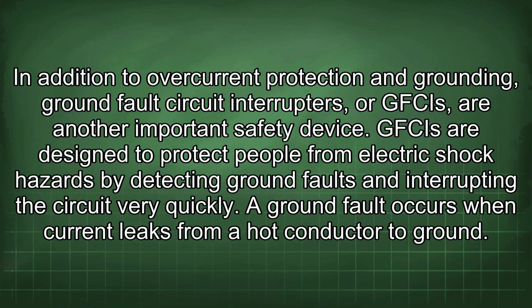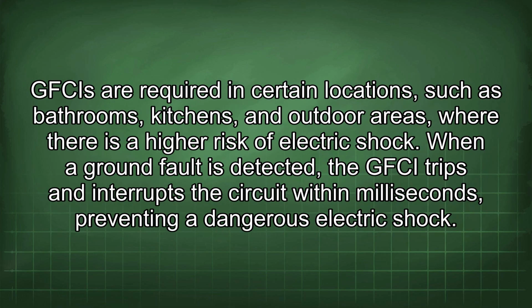In addition to overcurrent protection and grounding, ground fault circuit interrupters, or GFCIs, are another important safety device. GFCIs are designed to protect people from electric shock hazards by detecting ground faults and interrupting the circuit very quickly. A ground fault occurs when current leaks from a hot conductor to ground. GFCIs are required in certain locations, such as bathrooms, kitchens, and outdoor areas, where there is a higher risk of electric shock. When a ground fault is detected, the GFCI trips and interrupts the circuit within milliseconds, preventing a dangerous